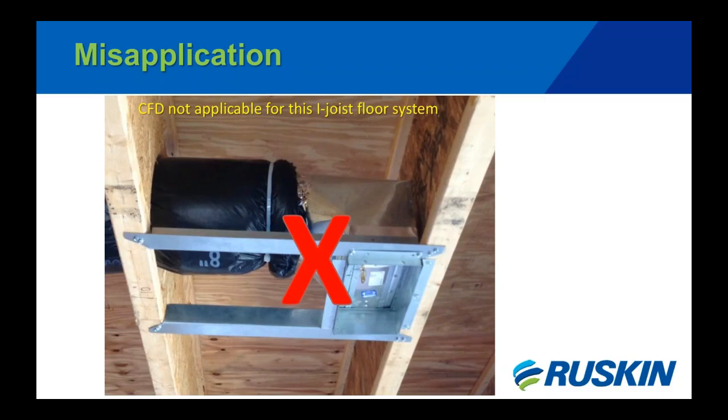Should contractors be insisting on getting the assembly numbers of the structure before they bid, if it's not documented in the contract documents? Absolutely. That's going to be another helpful measure, if nothing else, to help avoid misapplication. A lot of times contractors are buying products before they really know the facts of the assemblies that they're applying them in, or if they even can be applied. So we're always trying to make people aware: the more information up front, the better. It usually avoids a lot of problems and holdups on the jobs.